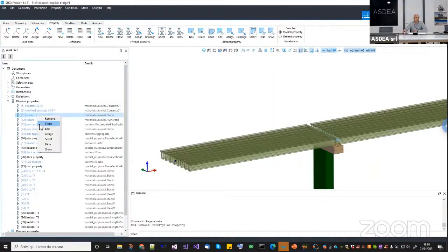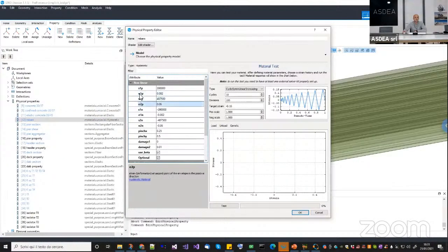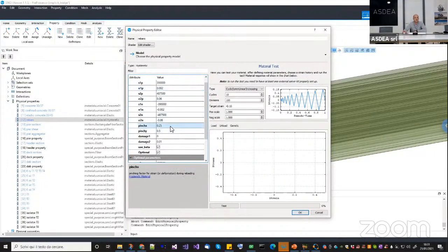Then we have an elastic concrete. As I said, why do I need an elastic uniaxial? At least 2 pairs of stress strain points, okay, in each direction. If you want, you can include the third one. And it can be unsymmetric in tension and compression. And the next thing is that here you can play with the pinching parameters to make this one like a standard elastoplastic material, or like a more peak-oriented material, or more like a pinching one.